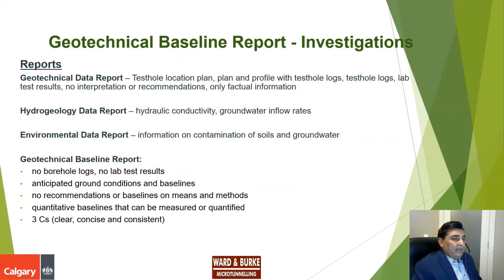And after that, we have to provide geotechnical baseline report. And geotechnical baseline report doesn't have any borehole logs, because borehole logs are in the data reports. No lab test results, because lab test results are in data reports. Then we provide anticipated ground conditions and baselines. Anticipated means we don't have to rely only on this investigation. We have to rely on the desktop study that we have completed.